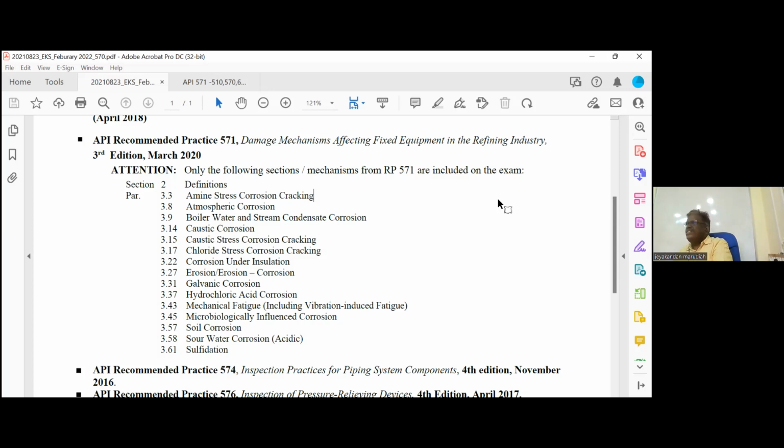And the corrosion probe, or ER probe, electric resistance probe, is not the same material. They are using sensors actually. Based on the resistance, they will measure how much it is corroding. That is called ER probes. Now, please understand, corrosivity and resistance are opposite. A high resistivity material will have low corrosion. Also, corrosion rate and temperature are directly related. When the temperature increases, the corrosion rate also increases. With this introduction, we will start the class.